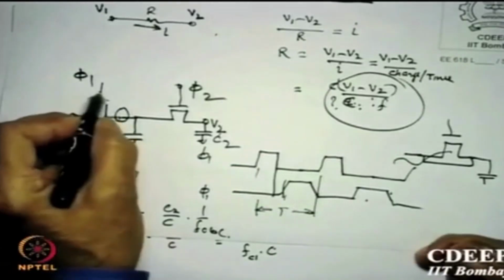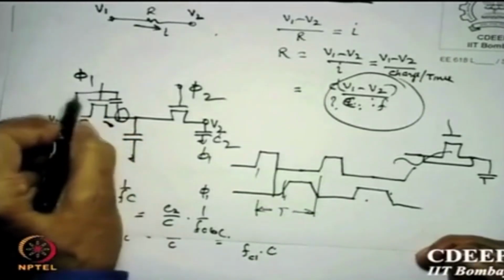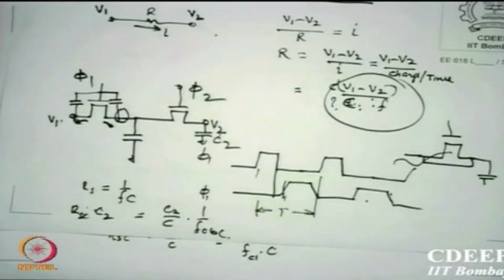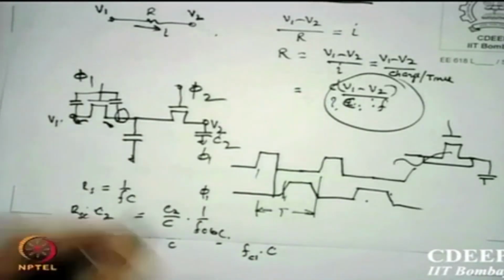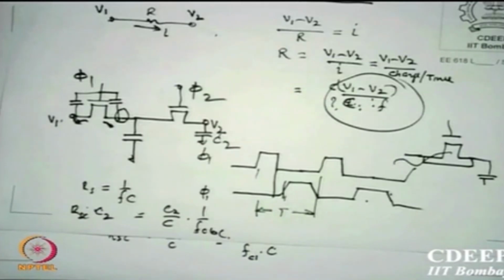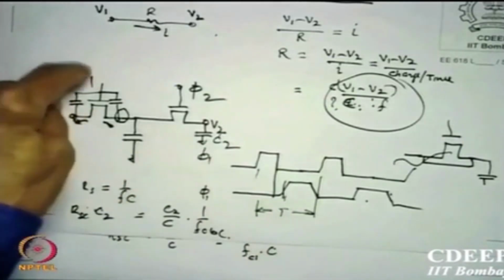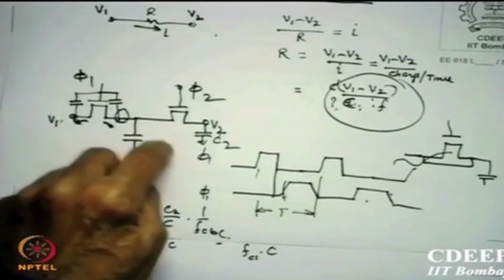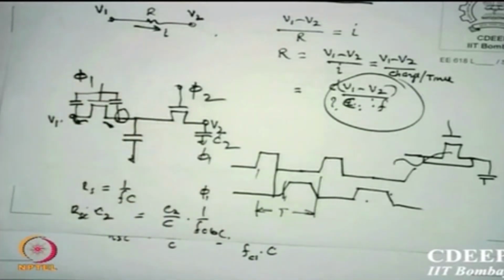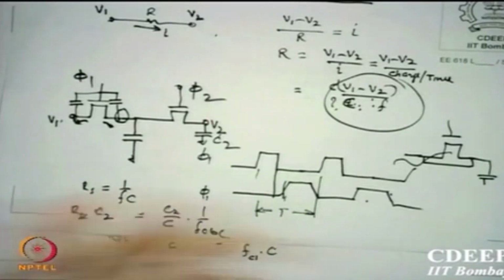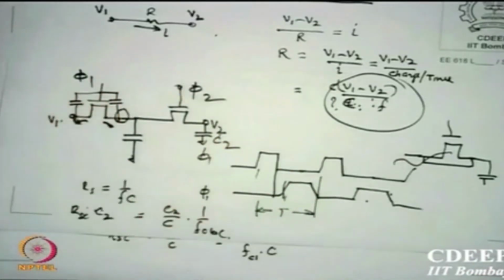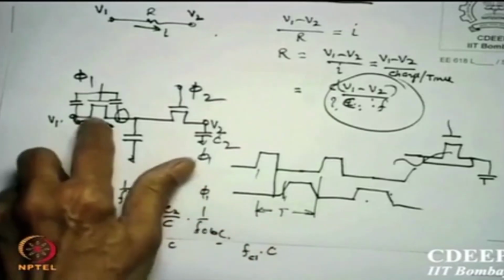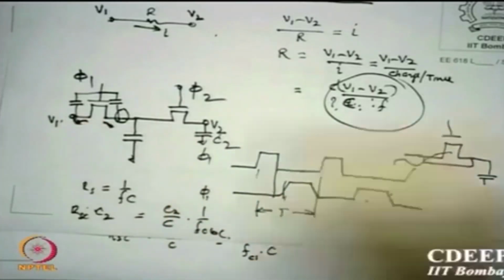The second problem with switches is that there are capacitances here. They share the charge, feed forwards, feedbacks, both are possible. So output levels are decided by what frequency you are turning on and off and what feedback it receives. So the final voltages are not exactly known, and depend on the frequency at which you operate. This is another problem. Most probably these feed forward and backward problems are very difficult to solve but can be minimized. Another method is to make it a CMOS switch, which will partly solve it.